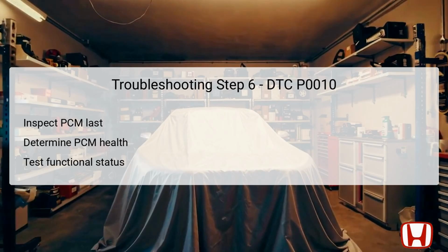Establishing whether the PCM is operating correctly is essential, as a defective control module can lead to persistent DTCs and performance issues. Ensure that all diagnostic data, codes triggered, and operational parameters align with anticipated function to make an informed decision about possible repair or replacement of the PCM. Only after confirming the PCM's condition can you affirm that all elements of the troubleshooting process have been thoroughly addressed.